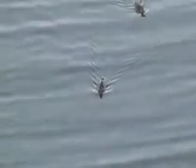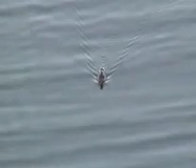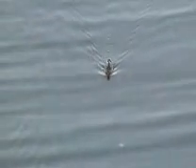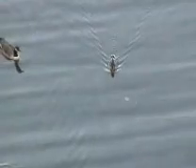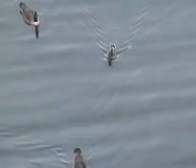This duck is swimming at a Froude number greater than 1, producing a similar wave pattern. There's a strong analogy between these liquid surface waves and shockwave phenomena in supersonic gas flow, where swept-back waves occur when the Mach number is greater than 1.